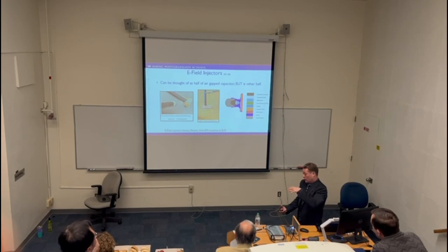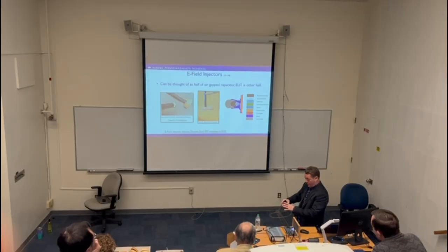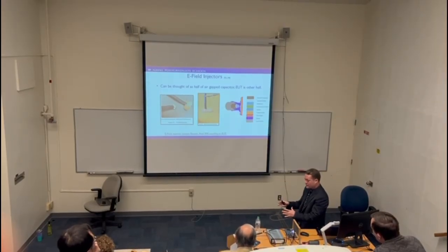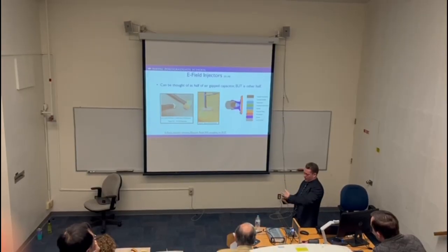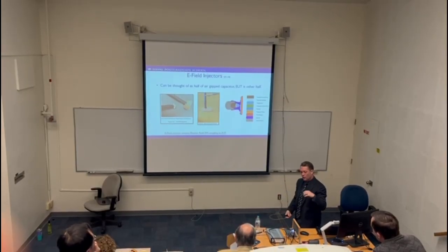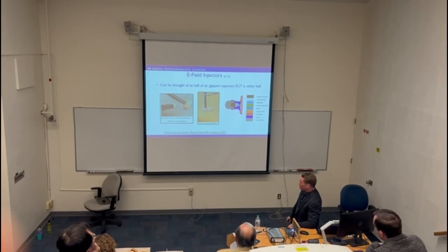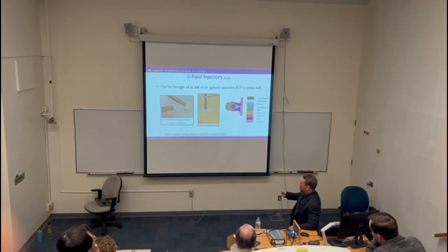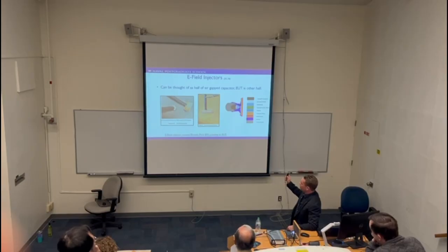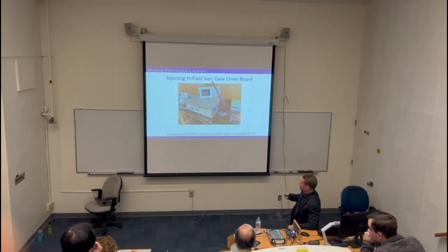Well, what happens when I send charge to the plate? It's either going to repel or attract a bunch of charge in all of the common circuitry that is in that power that's all referenced to the same chassis type of circuit. It's a mesh circuit. So that creates all of this unified charge all coming together to be attracted to that charge that's on the plate or repelled from it, depending on where you're at in the period of the sine wave. And it causes mostly common mode type coupling. Another type of coupling, again, we haven't seen the drastic effects of the E-field injector as we did with the H-field, which is why we really chose to focus deeper into the H-field.